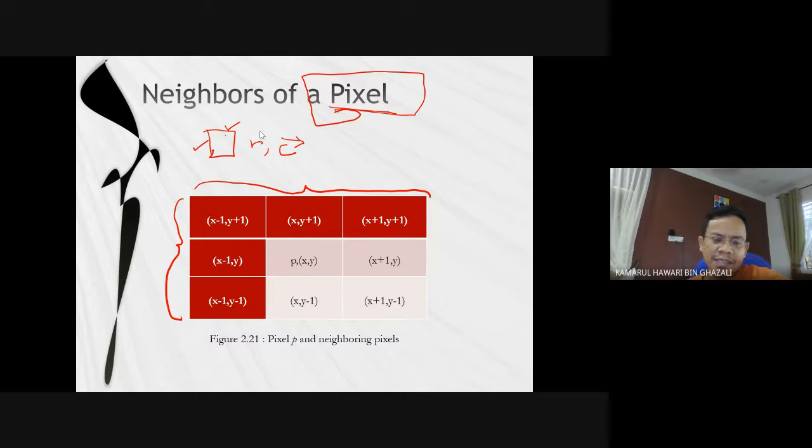Even in machine vision, if you use an 8 megapixel or maybe 4 megapixel camera, or 12 megapixels, it is more than enough. If you go above 12, it is already considered higher, because we need to process the image.